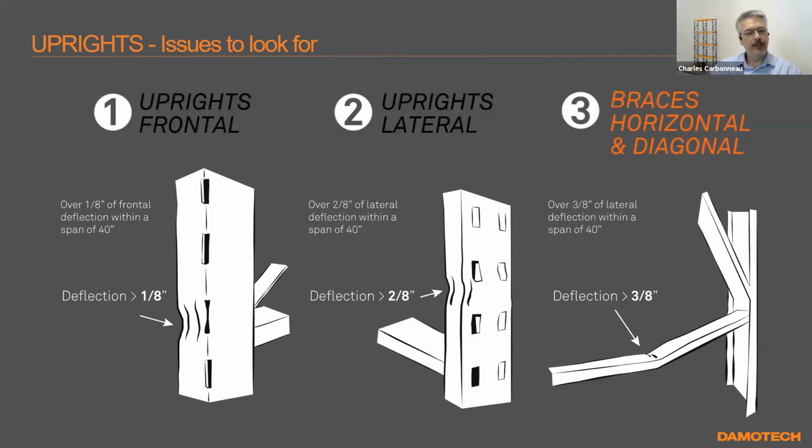then you might say, well, the bottom braces, I definitely need them to work in tension and compression. I'm not going to tolerate beyond anything that's 3/8 of an inch. But typically you would say, at 3/8 of an inch of deformation, I'm entering that gray zone. When I'm at 6/8 of an inch or 3/4 inch of deformation, that's it. I replace it. Seismic or non-seismic, that's my limit. So that gives you a little idea.